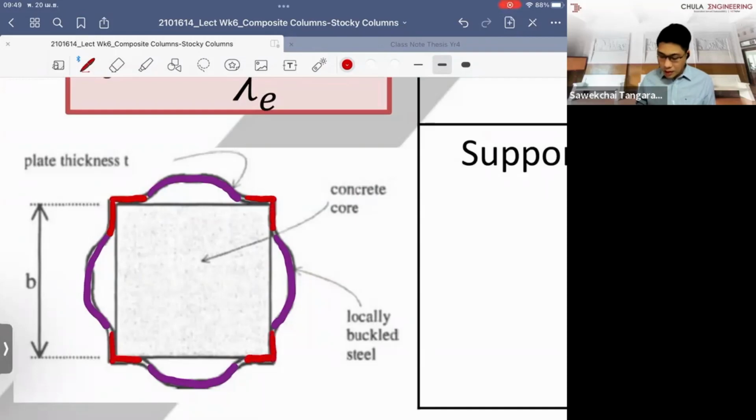So in this concept, what they say is that when we're looking at the total width of the section, we're looking at here, which is from the internal edge to the other side, and we call it B, right? And the effective width we are looking for is the width that is governed by the red color, which is undeformed, and we call it the combination of this, right?